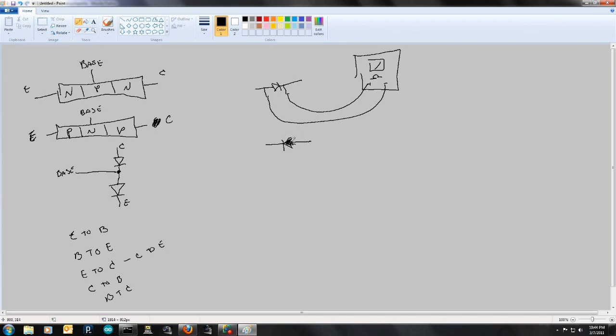Bad diode. We'll just color that in. Now, if you're measuring him in positive here, and then common or negative. So you measure it in one direction, then you measure it in the other direction. And basically you can take a known good one and see what all your measurements are going to be. And then if any of these are incorrect readings on any of these measurements, it indicates that the transistor is bad and it should be replaced.